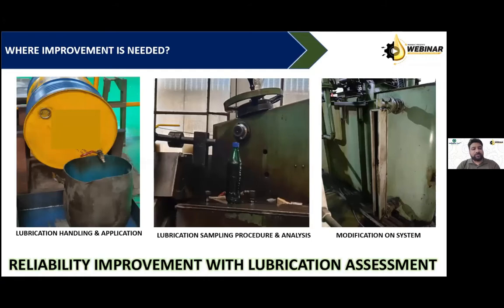The lubrication handling starts right from the area where you have stored the lubricant. So you must start introspecting whether you have got the right tools and tackles to maintain the handling devices at your lube cell. Do you have a separate team or a separate cell which is capable enough to handle the incoming lubricant and to fill the lubricant into your equipment? Do you have a cell or a condition monitoring unit which can actually sample the lubricant in a proper fashion and not in an ad hoc or non-professional fashion? Are they doing the analysis in a proper way?